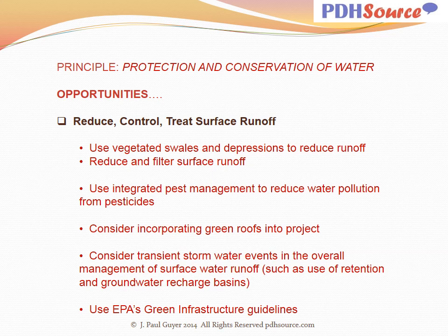If the runoff from your site is going to, because of what's going on there, contain grit or oil, things like that, you might want to seriously consider designing into your site grit capture chambers or oil separation chambers to capture the grit and the oil and prevent them from moving off the site in the runoff.